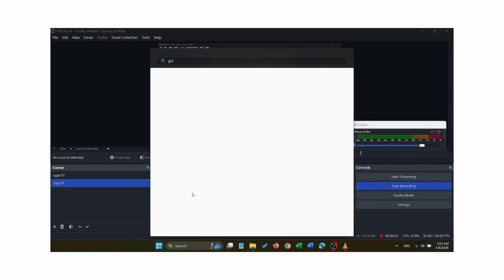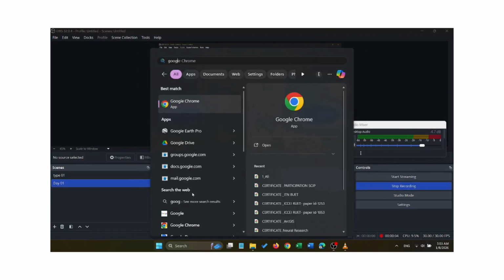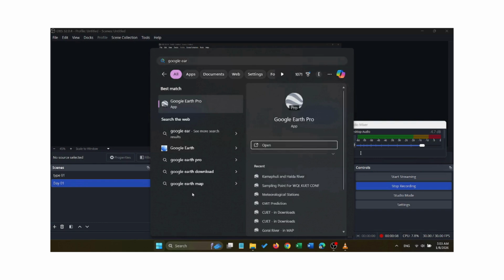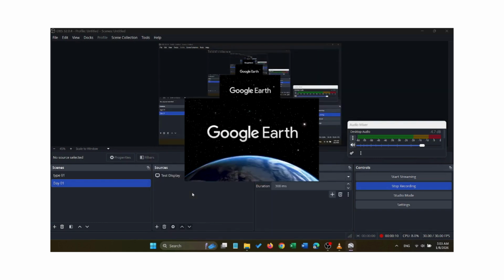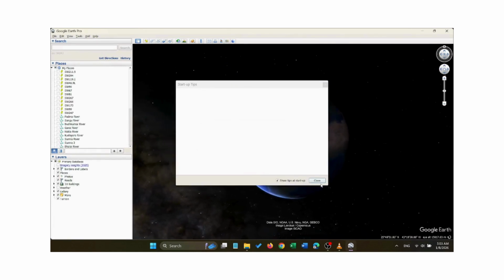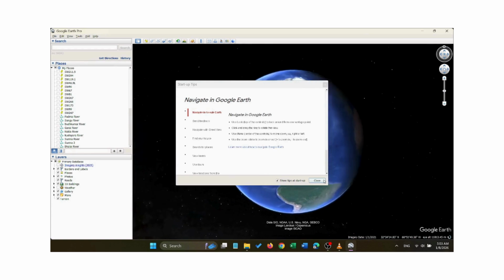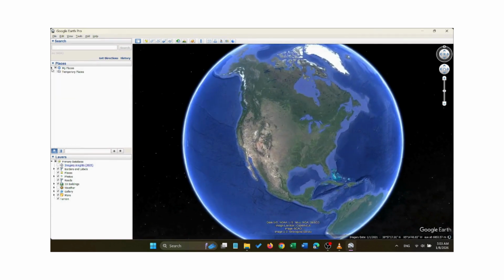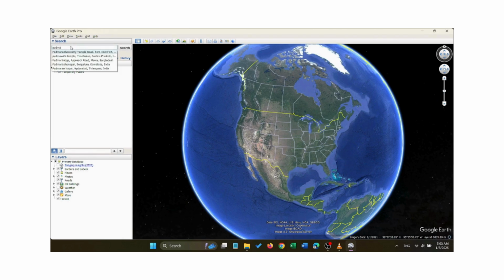In this class, we try to learn in a study area map how we can plot the concentration of pH, DO, or BOD, COD, or any other parameter. So for that, initially we have to open Google Earth Pro, and then in the search bar portion, we have to search the places for drawing the study area shapefile.